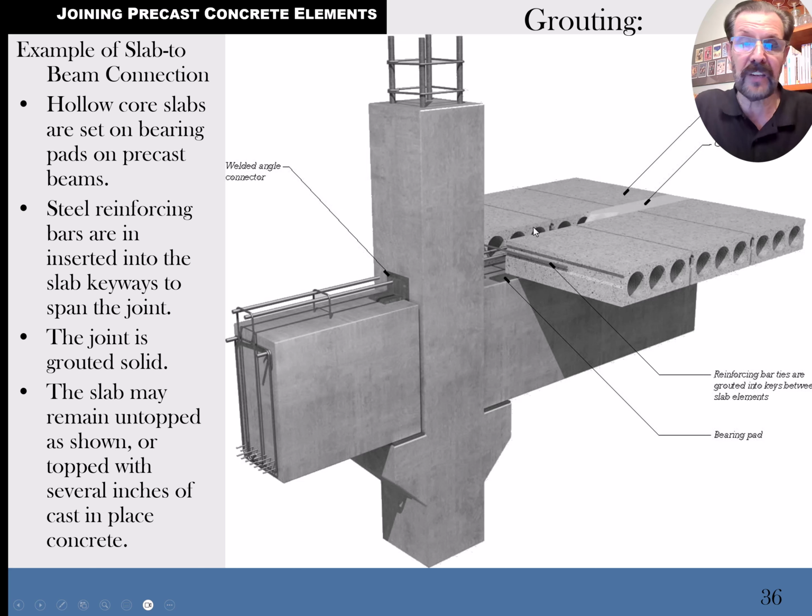But to get a connection, they literally took and tied some rebar in here, running the length of the beam inside of those stirrups that are sticking up out of the concrete beams. And same thing over here. And then they pour concrete in here. So by pouring concrete across here, some of it will spill into the hollow core slab cores, the hollow part, a little bit, maybe 12 inches in there or something. And they fill this up and even into this.